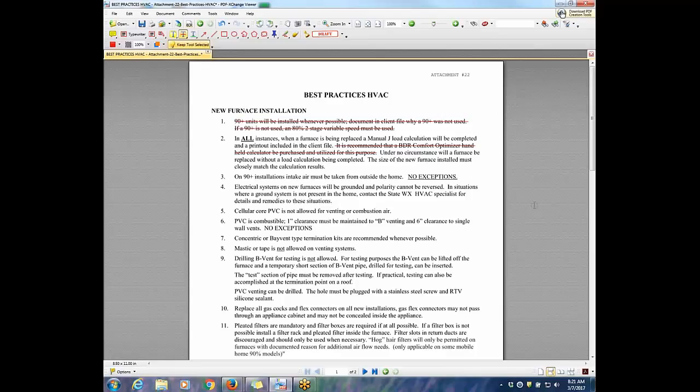We usually do manual J's before we actually install the furnace or the equipment. Okay, good. Do you use one of the manual J software programs for that? Yes. Awesome. So if you know you're going to weatherize the house, do you do your manual J and use what you suspect you might put in? Like if you know you're going to do insulation in the attic, maybe you run your manual J assuming that insulation is eventually going to go in? Yes, we do. Okay. That's a good approach.